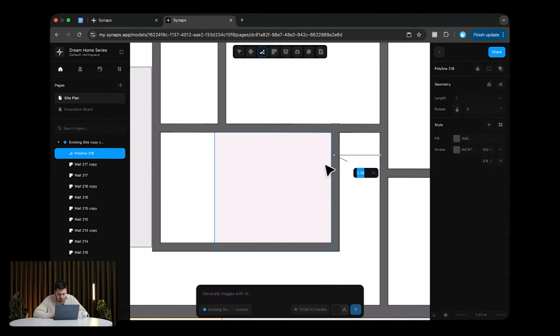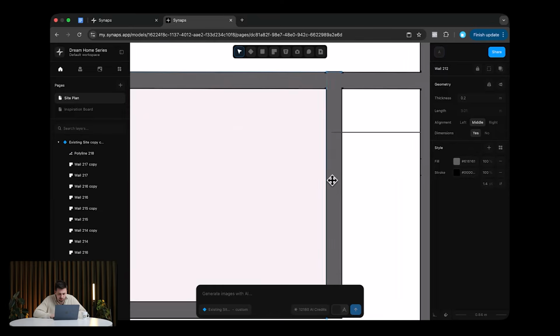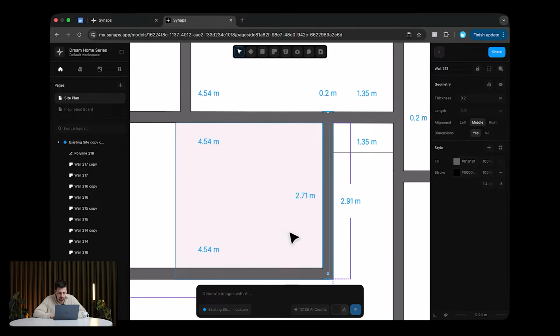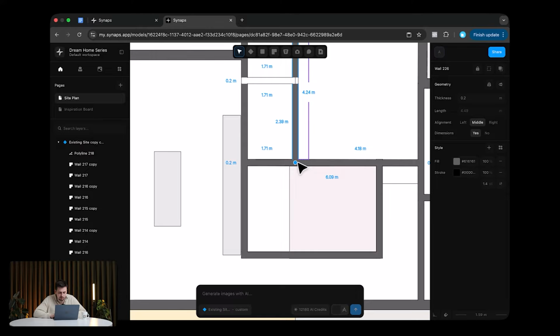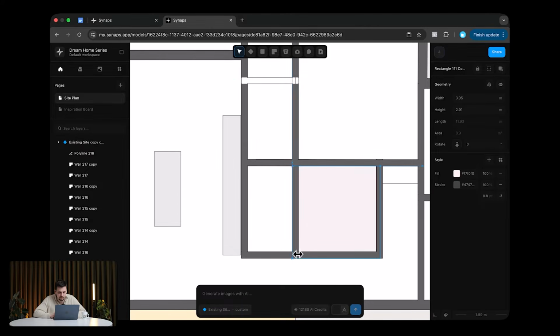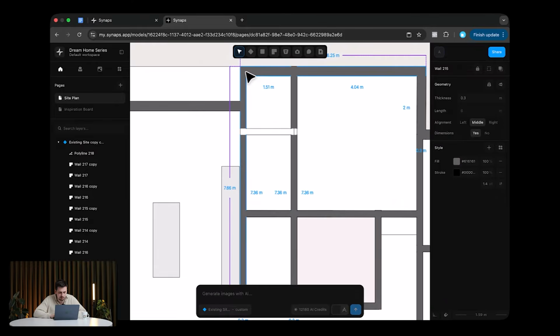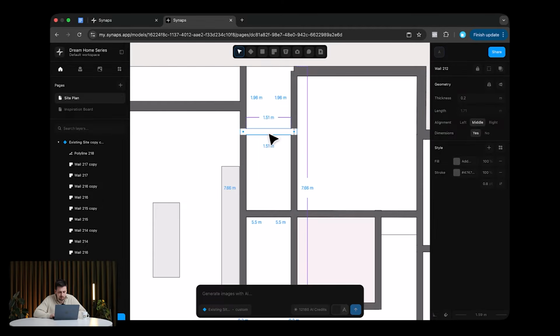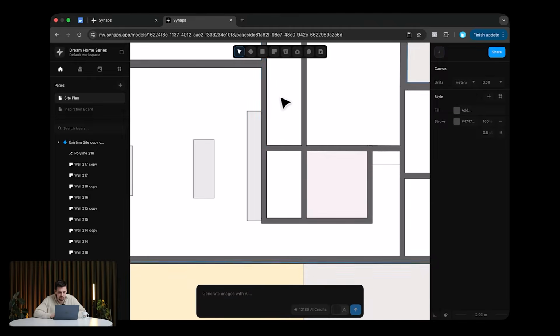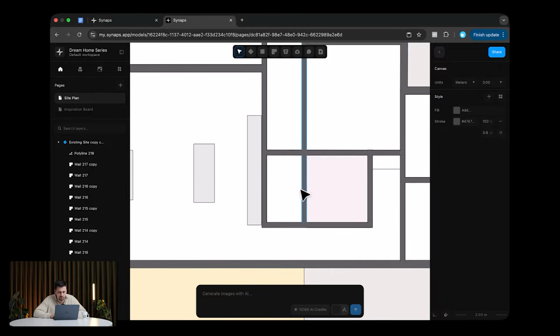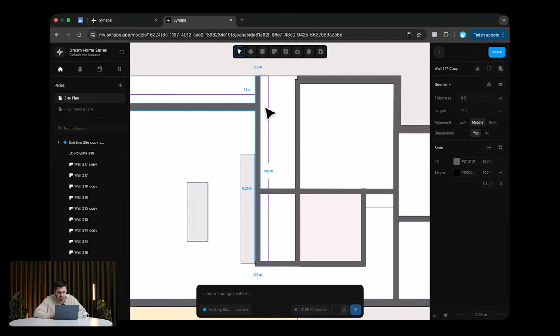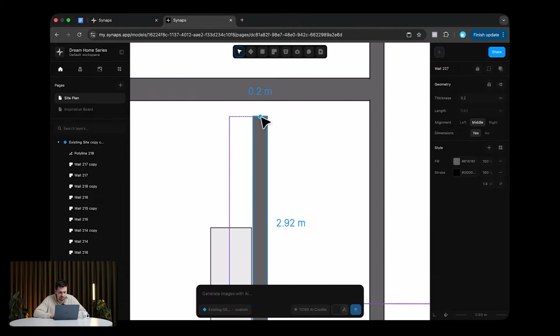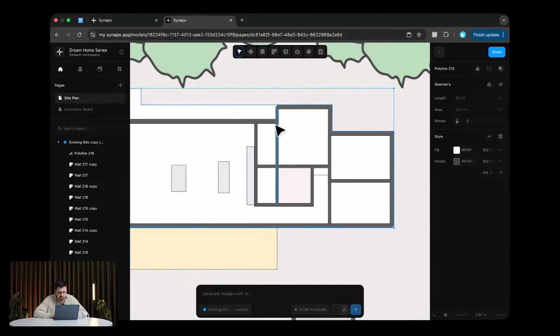So this could be at 1.2 meters in terms of a wide enough corridor, and then I could just bring this up to here, and then I could take this off completely, remove this wall, and then this can be the pantry, and then this can be the laundry room, because then you will also have some sort of connection with a bathroom, which I think is good for water installations and everything else. So I can close this off, but basically what I did was I just moved that vertical wall from here to here, which is still not the biggest thing.